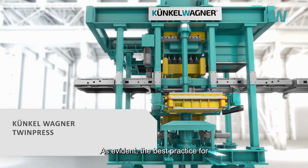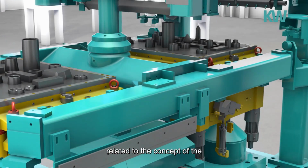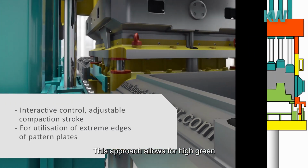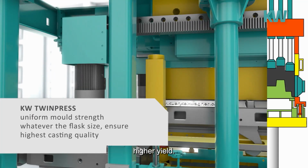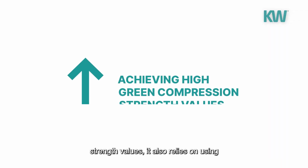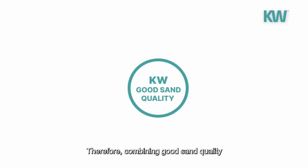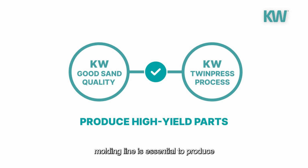As evident, the best practice for producing cast iron parts is closely related to the concept of the Kunkel Wagner tight flask molding line. This approach allows for high green compaction strength and, consequently, higher yield. It is crucial to emphasize that achieving high green compression strength values also relies on using proper sand quality. Therefore, combining good sand quality with the KÜNKEL WAGNER tight flask twin press molding line is essential to produce high-yield